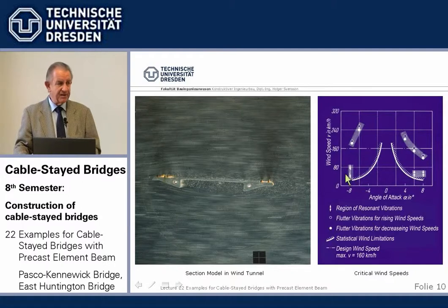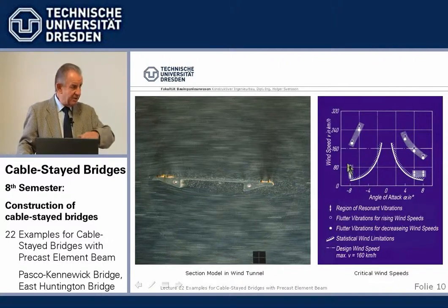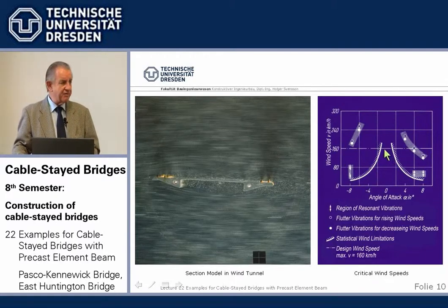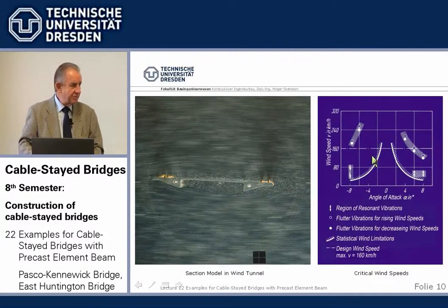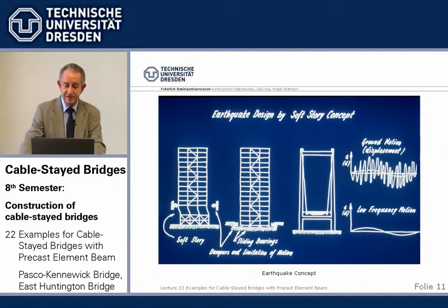And then the other is vortex shedding, which traditionally occurs at low wind speeds, but although it occurred at low wind speeds, it was beyond the wind limit because it occurred only at steep inclinations of 8 degrees. So with this picture, we could convince everybody who, not knowing anything about aerodynamic stabilities, just by showing, look, all these phenomena are outside our limits, check it off, well done. So that was how we convinced our client that this is safe.